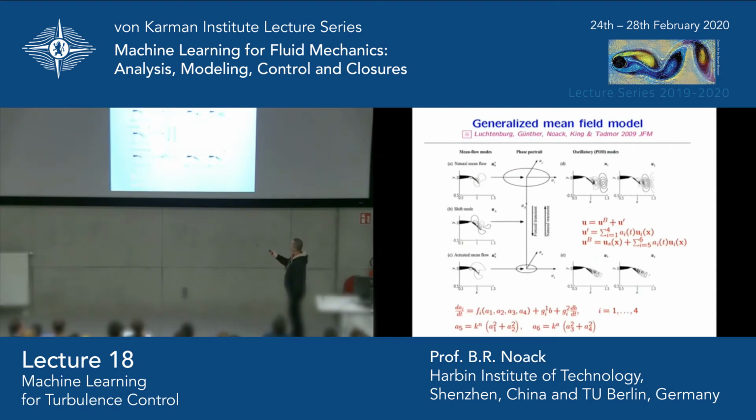So here you can have a forced transient from this limit cycle or a natural transient back. And this shall be described as such a dynamical system. The fluctuation drives the base flow. So we derive the base flow effectively from the Reynolds equation, and the actuation is modeled essentially by the blowing and the suction here, and its derivative. The reason is the following: we want to have a cosine and sine signal, and we never know to which phase our actuation communicates.